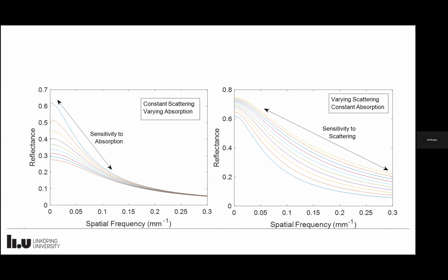So now that we have this calibrated, the next sanity check, and again this is just looking at a single pixel essentially, you can look at the image. For the calibrated reflectance, you can ask the question: is it between 0 and 1? If you have negative reflectance values, that's non-physical, and there's something wrong with the calibration. Is it greater than 1? Well, that's obviously also something wrong. If it's between 0 and 1, there still could be something wrong, but at least you are eliminating the obvious case.